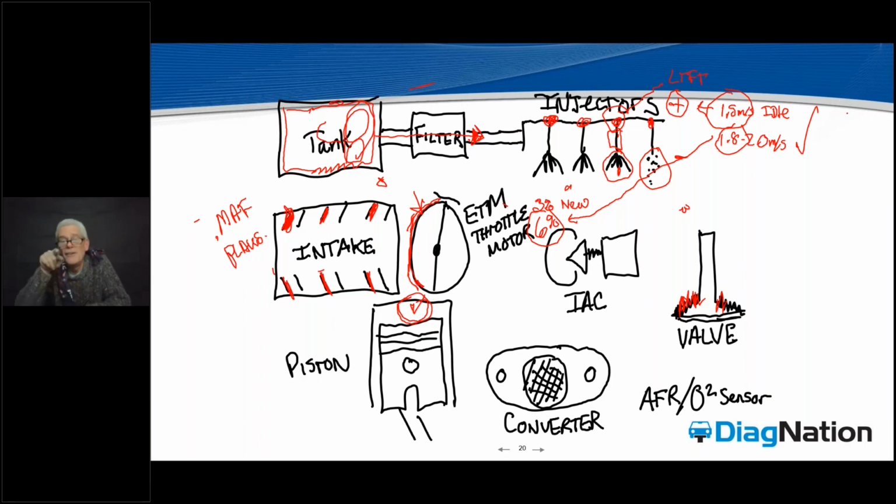What's going to happen is the longer that throttle motor keeps cranking open, the injectors are going to keep moving with it on a GM car. On a Ford, you're going to see it act much more like a diesel, and you're going to see air-side adjustments. That fuel trim will stay right where it is.